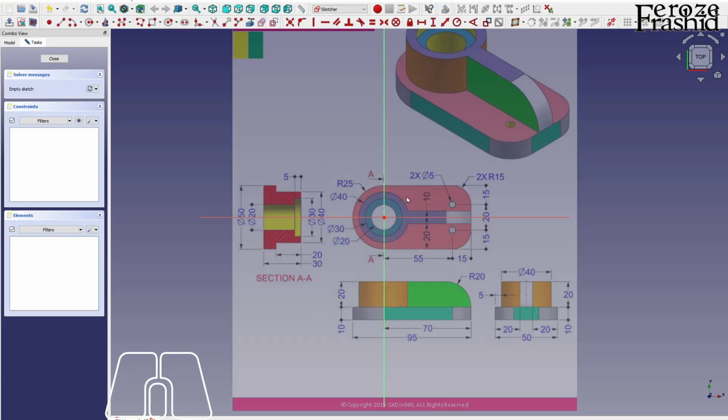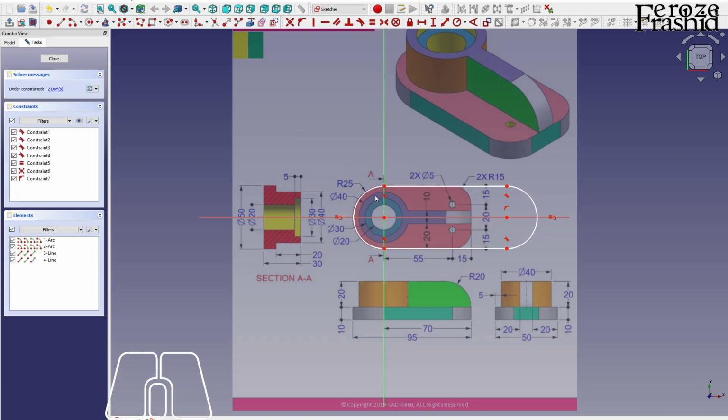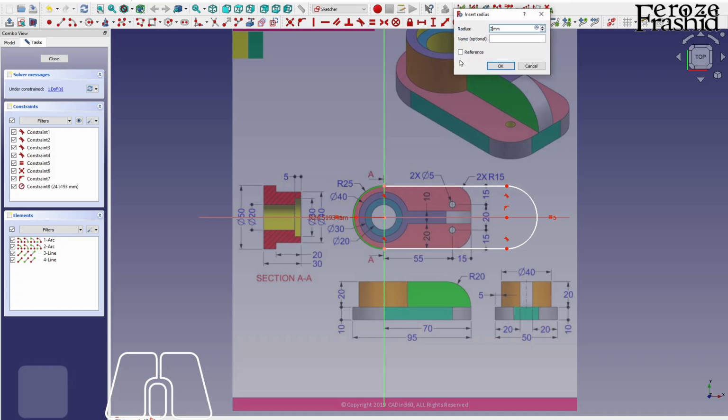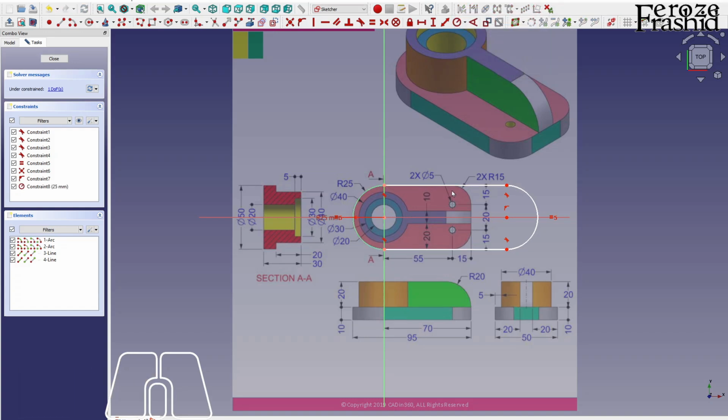And I want to start with this base, which is half slot, half rectangle. So let me go ahead and start with the slot. All right. So this outer radius is 25. I just want to pin it down there before I do anything else. I'm going to go ahead and delete this. Bring this a little closer. Right, and maybe close it as a rectangle. Now I want to make these two horizontal.